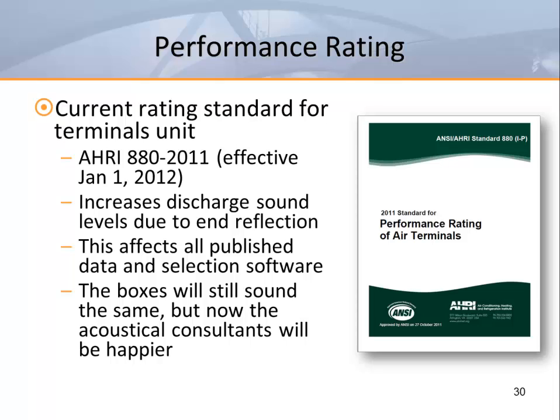The biggest change introduced in this standard involves end reflection. End reflection occurs when airflow undergoes rapid expansion or contraction. This commonly occurs when air discharges from an outlet. Air that was confined by ductwork suddenly expands to fill a room. When this occurs, a certain amount of sound energy is reflected back towards the source rather than traveling to the room.